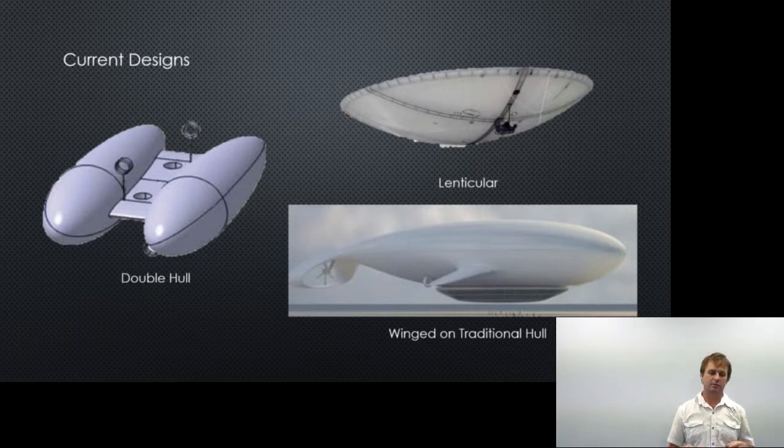Rigid designs are basically an outside frame that the gas envelope sits inside, and that was generally for really big, heavy weight airships, so we've moved away from that to a non-rigid design and just using the envelope that holds the gas as a means of where to make up our main structure. And following the main structure, we had different types of designs we could use.